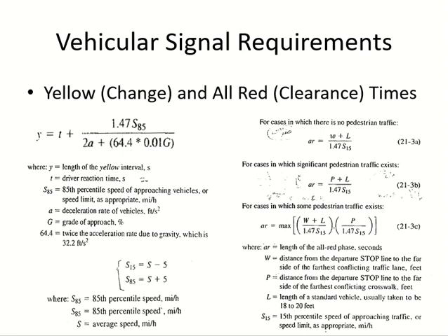In all of them, we are using two common things, S15 and L. S15 means 15th percentile speed. How do we get the percentile? You have to draw the curve. If you don't have the data, you cannot draw the curve, then the shortcut is this one: mean minus 5. Clear?